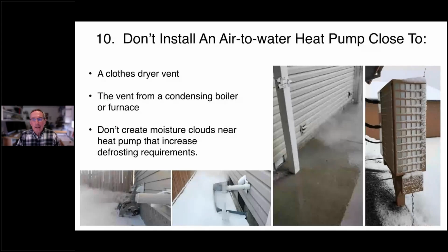Okay. Here's another one that, again, you think about these things sometimes after you've seen the installation, but when you have closed dryer vents or vents from modulating condensing boilers, both of those can produce a lot of steam. And if we have a heat pump mounted 4 or 5 feet away from a vent like that, with the right wind conditions, we're basically just going to bathe that outdoor unit in this very moist air. And that's just going to create more and more need for defrosting.